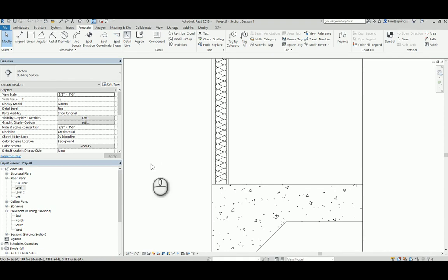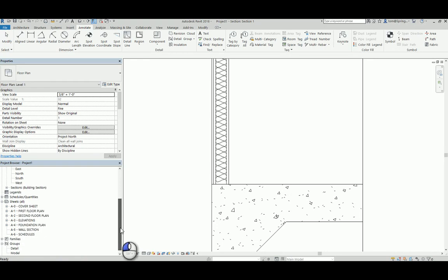And so to put this in here, I would get this under my content over here, and I would go over here and I would get that under my families. And under my families here, it's actually under detail items. And under detail items, I have a few things out here. One of the ones that I want is nominal cut lumber. The nominal cut lumber is going to give me 2x4s, whatever size I have. In this case, I want a 2x4.